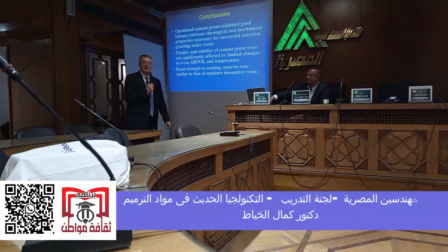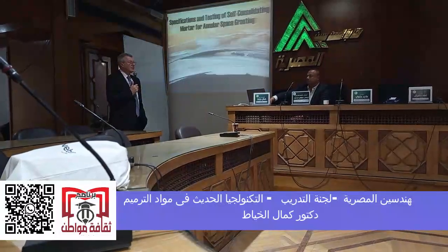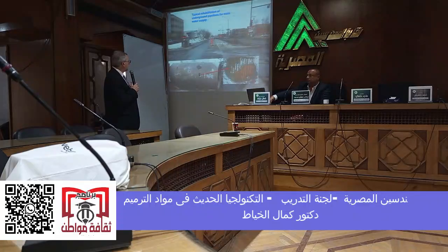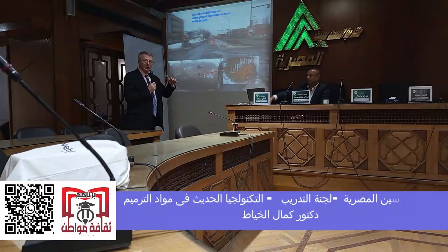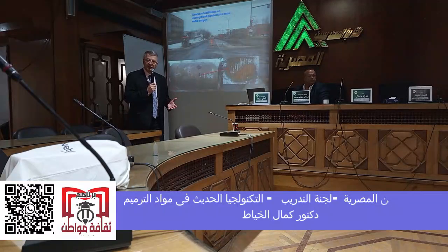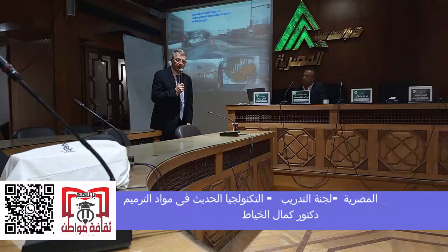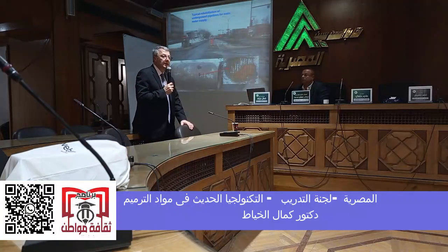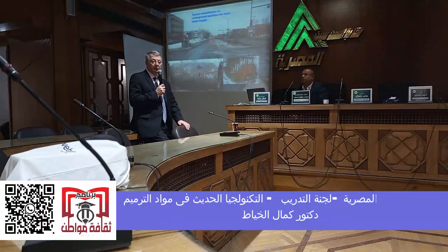Okay. I don't know how much time you want to spend more. I was going to talk to you about the repair of these water lines. Again, this is downtown Montreal, and they have the water lines, the pressure pipes. Because of the penetration of salt from the pavement, eventually they corrode and snap, and then you have a break of water lines, and for a long time people don't have water. So from time to time you have to repair them.